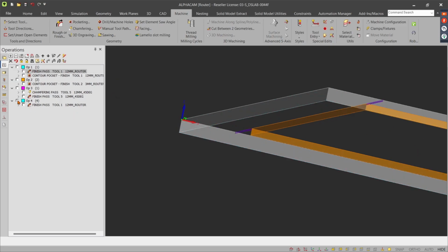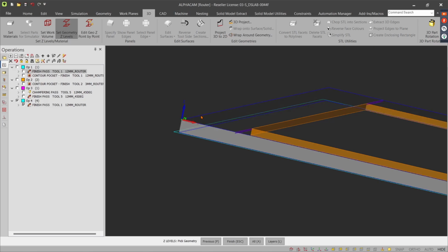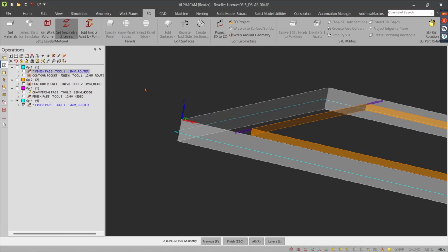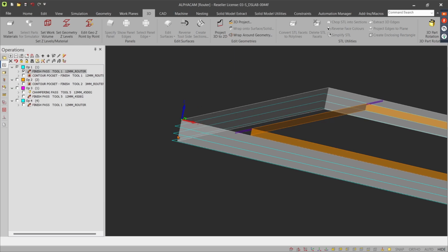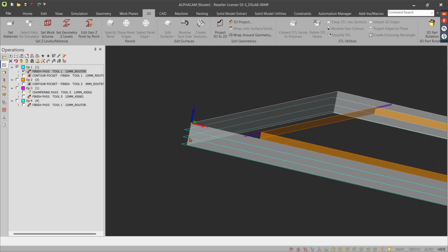If we had doors that were actually supposed to be, say, 24 mil, if I click on that one, or even say 30 mil, with our toolpath, you can see they both highlighted blue because the geometry they're associated to is altered. If I update this bottom one, nothing happens because we've got a parameter of -18. But if I update the top one, it adds an extra 2 slices in there because it's going 10 mil deep at a time. So that is how we can automate it.